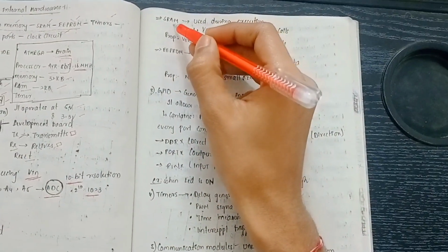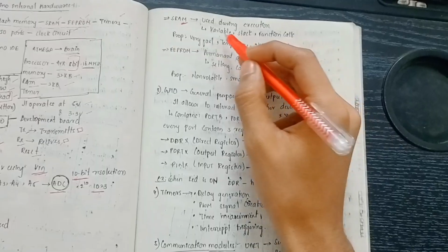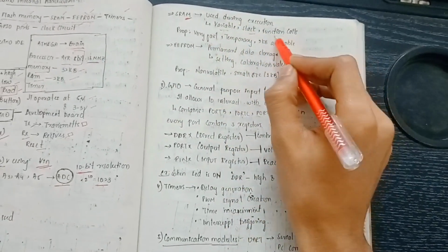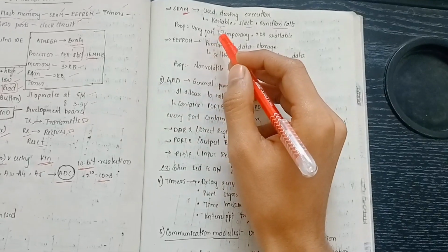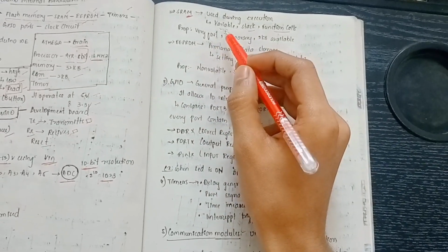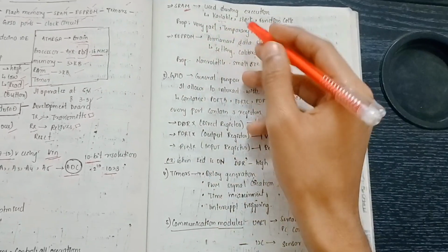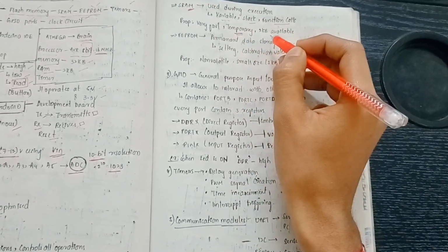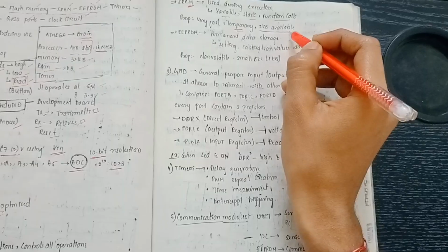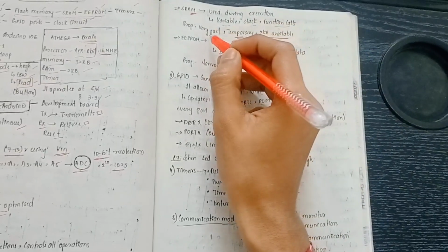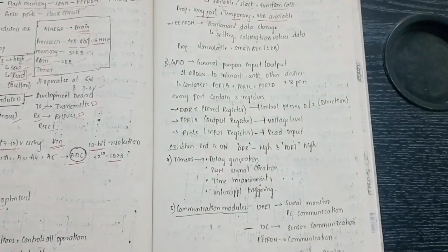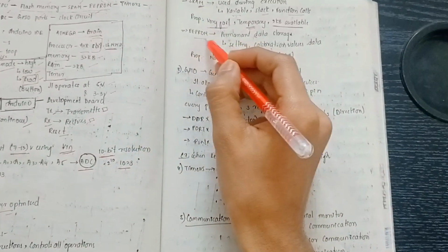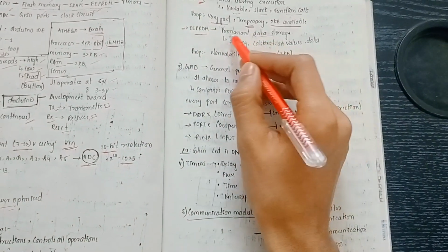Here comes the second type of memory, SRAM, which is used during execution to store variables, stack and function calls. During the code, we might adjust variable values which we need temporarily. It only has 2 KB of memory for storing them, and it's very fast as we need to change the values successively.